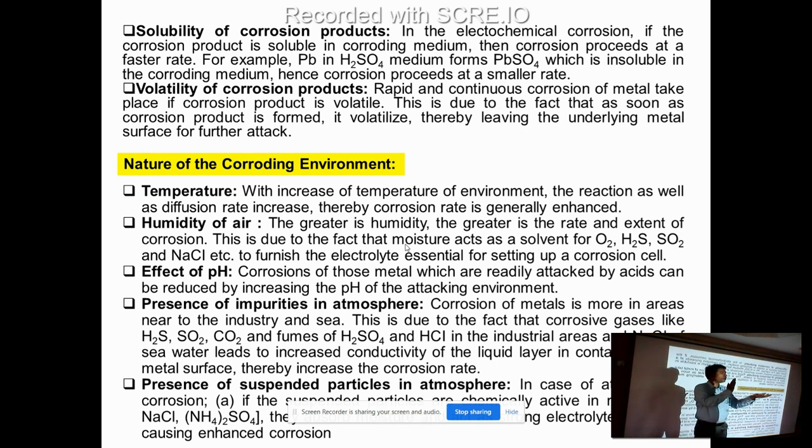That's what I'm saying. Iron may form iron oxide, but this iron oxide film will be quickly peeling off from the surface. That's what we observed with the nail. More corrosion takes place because of the sodium chloride there. The sodium chloride will act as an electrolyte. The chloride ions, again, are highly oxidizing agents, as we have seen in the electrochemical series. So this chloride tries to form a good electrolyte system. Passage of ions and electrons will be much more. So more corrosion, and more corrosion means more surface will be corroded. At the same time, this corrosion product is soluble. If it is soluble, what does that mean? It quickly dissolves and comes to the bottom.